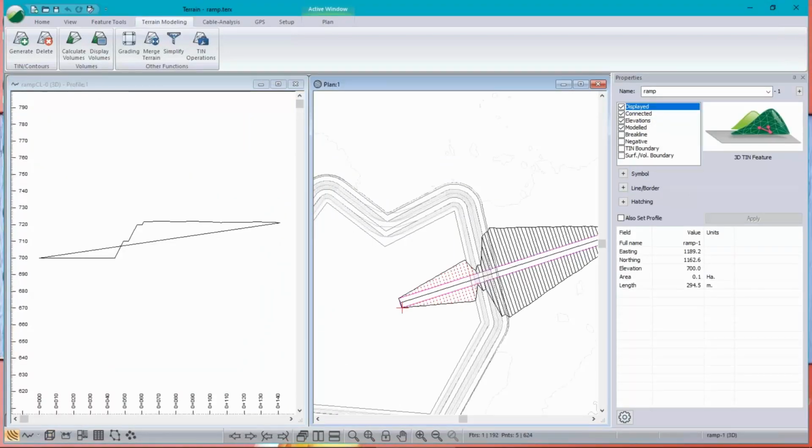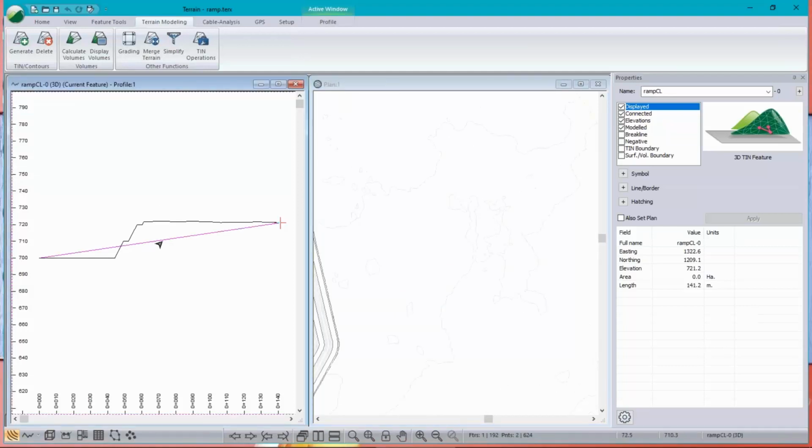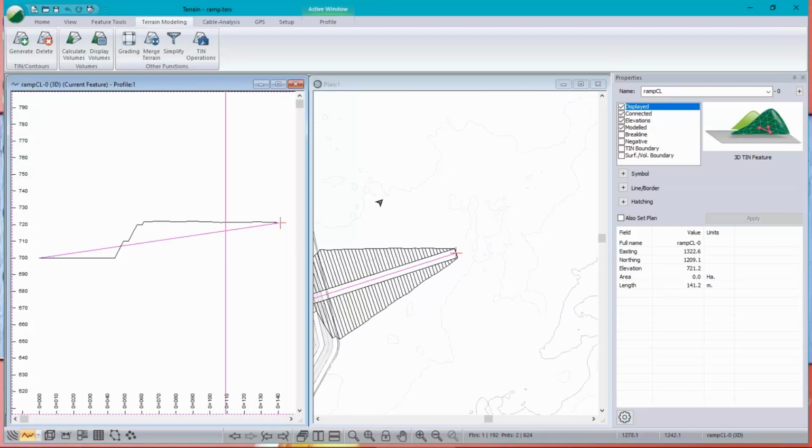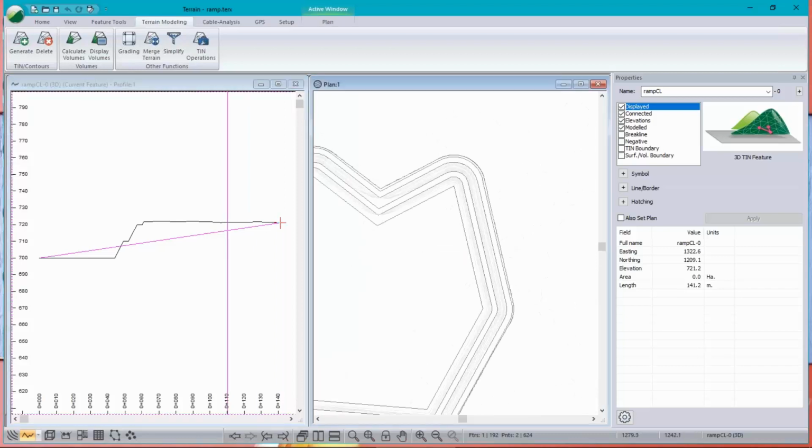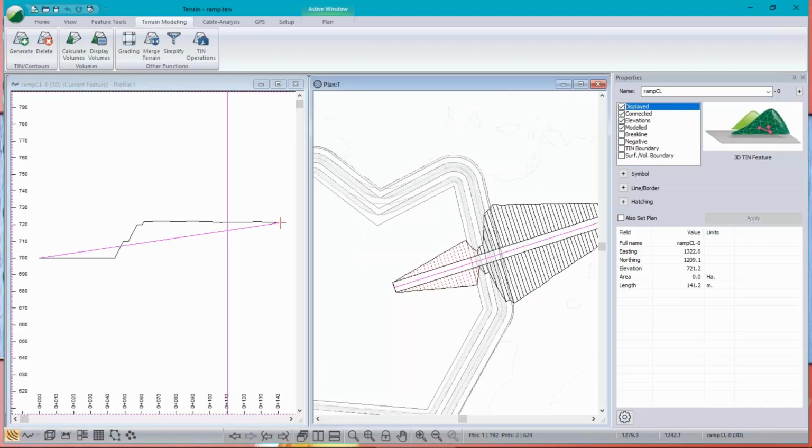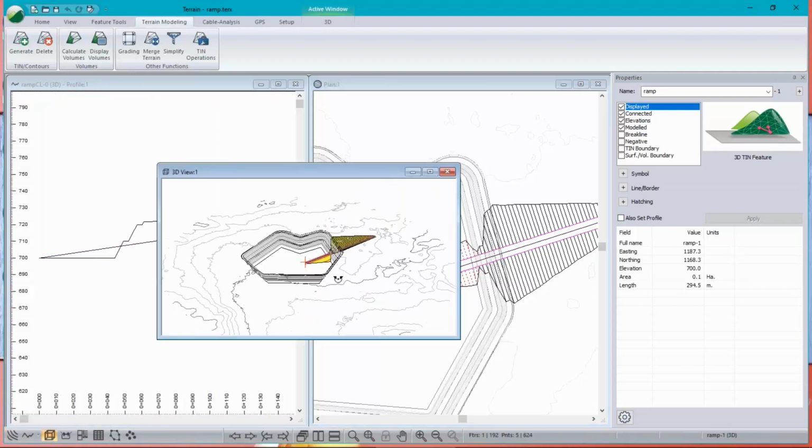This is another way to get into the pit. I was careful to draw this feature, that's the center line, at the right grade and terminate on the ground and terminate at the bottom of the pit. And then I buffered it to make road edges. And then I selected those things and did a grading operation and created this surface. So it looks like so.